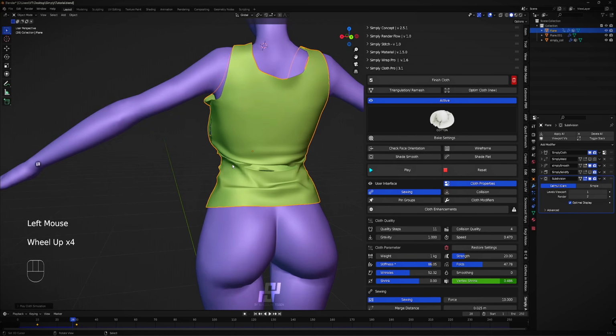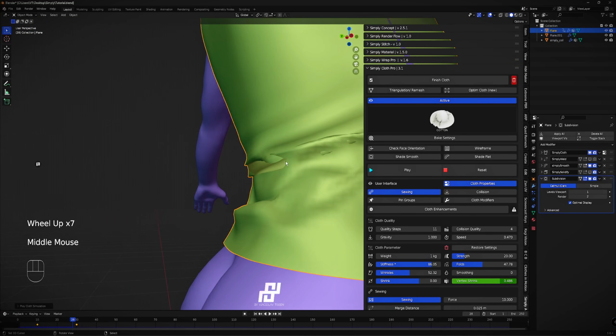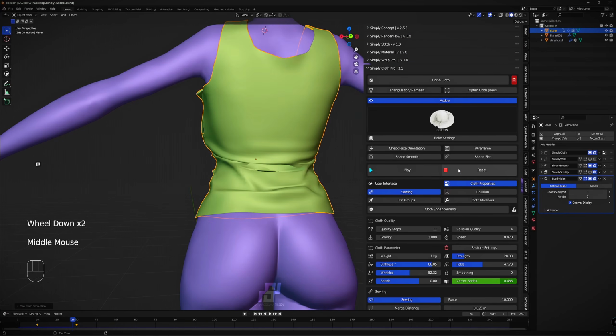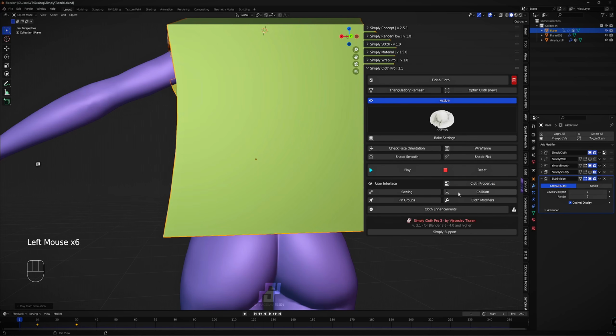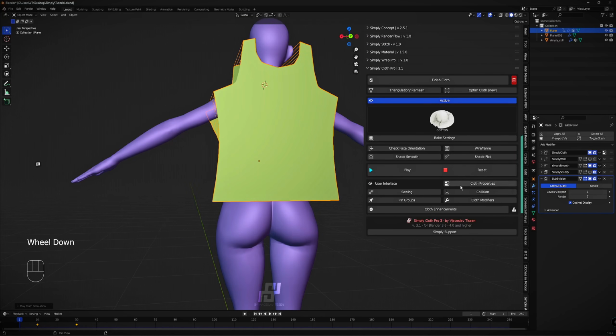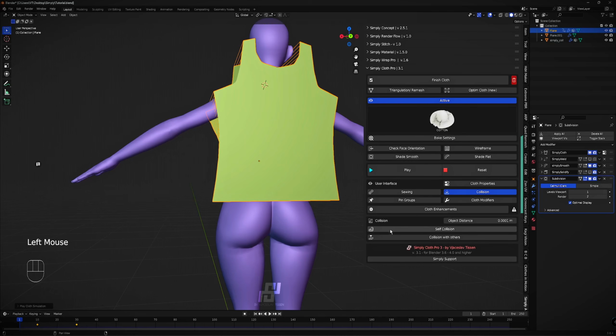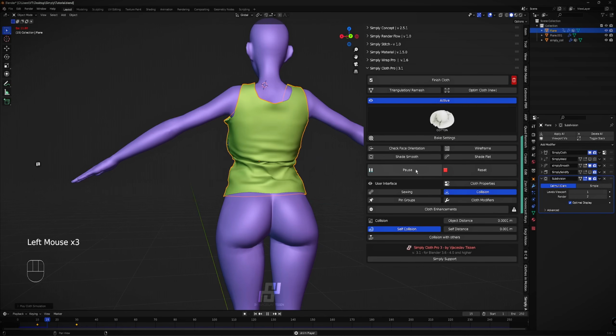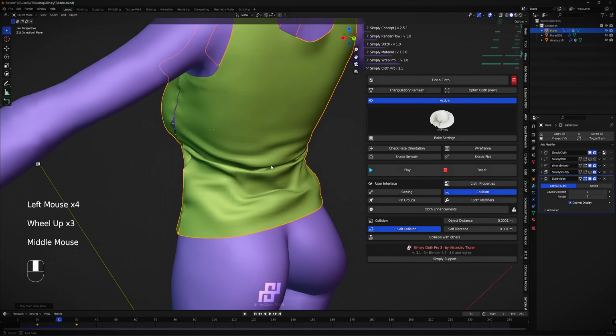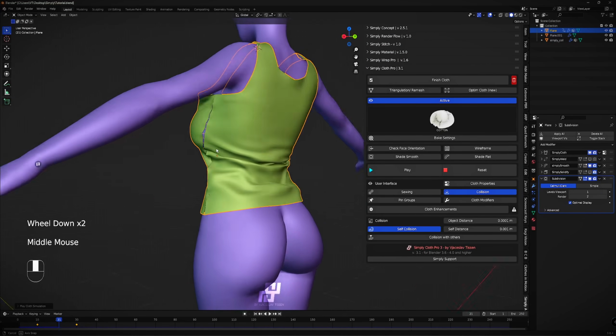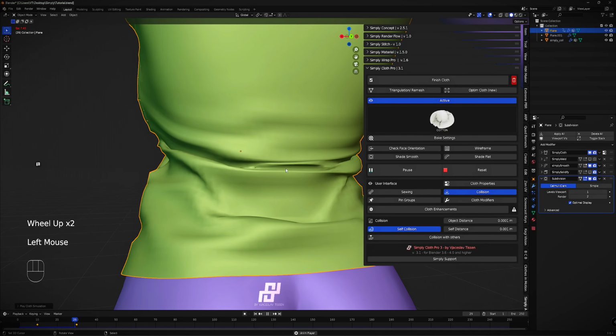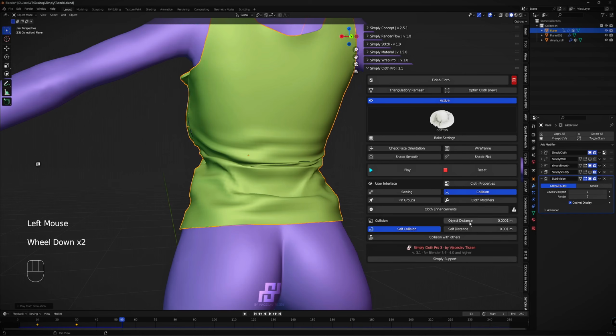And what you notice here is an intersection within the cloth itself. For this, you just open the collision part of the cloth object and set up self-collision. That's it. So the performance would be a bit slower, but you have no intersection anymore between your cloth. So a bit could happen, but not that much. So depending on the distance, of course,